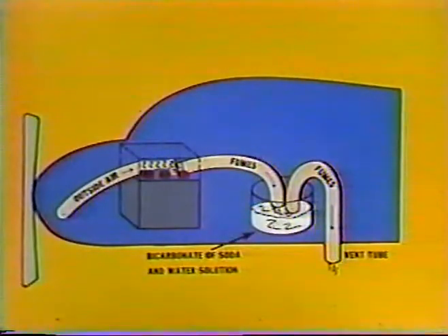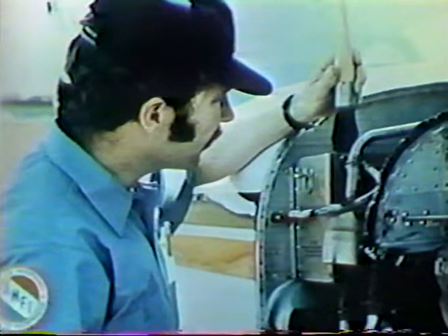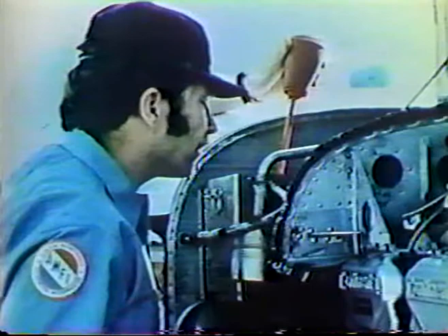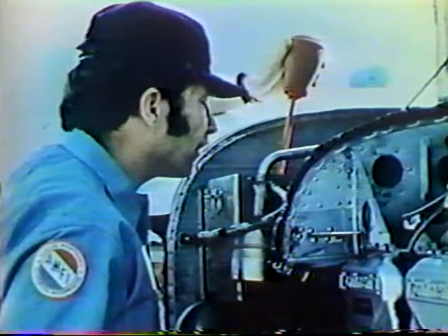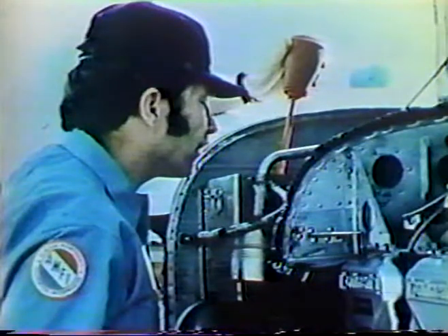In some aircraft installations, fumes are directed through a sump jar containing a bicarbonate of soda solution. Here, the fumes are neutralized before they exit the aircraft. Corrosion should be neutralized and the area painted with acid-resistant paint. The electrolyte level should be regularly checked and adjusted with colorless, odorless water, distilled water if possible. Do not overfill. Electrolyte should not be added for normal battery servicing. Do not add water if the battery will be subject to freezing temperatures before use, as water will not mix properly with electrolyte and freezing damage may occur.